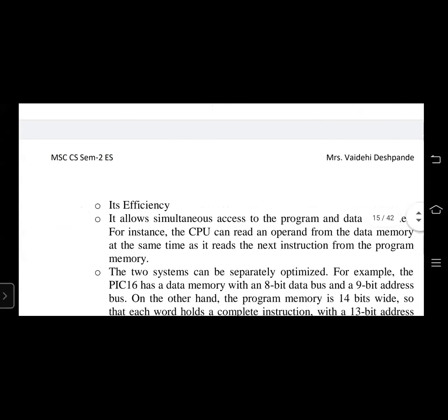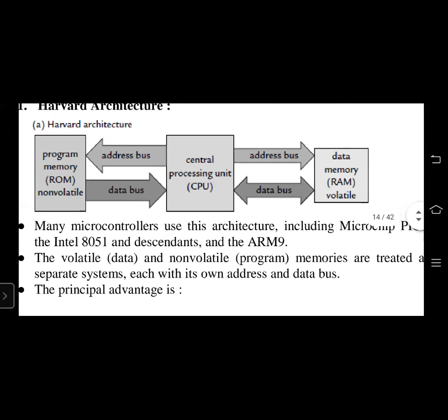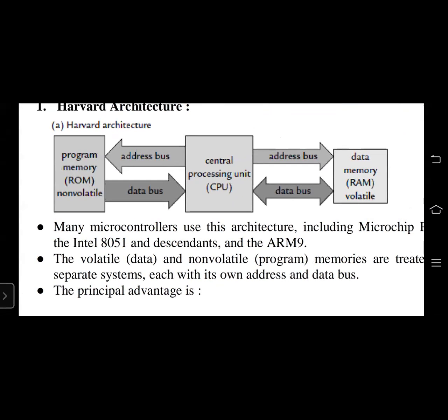So this is your address bus and data bus with the RAM. With the ROM, again the address bus is unidirectional, only from CPU to ROM. Now ROM is a non-volatile memory, so data will be stored permanently. And the data bus, again, is only from ROM to CPU. Fine. So that is the architecture, diagrammatically shown, of how the hardware architecture is.